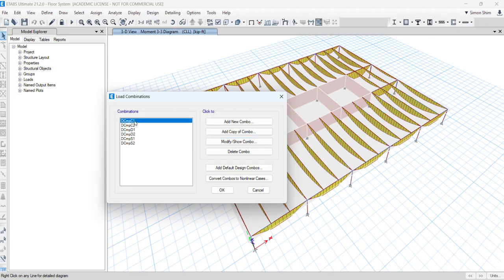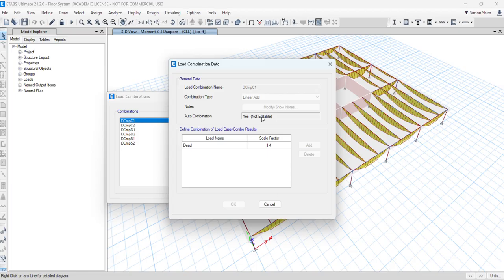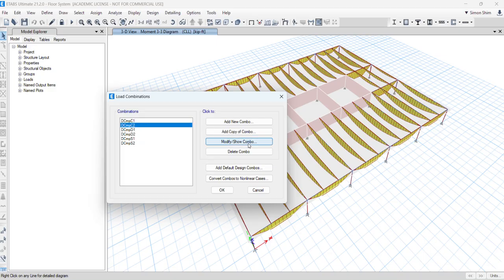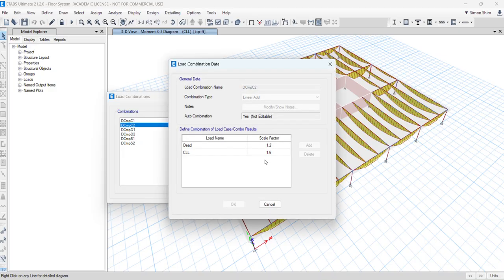But it also checks the phase one, which I'm going to explain in the composite floor framing design, because of the construction sequence. We need to check the beam size and its behavior under temporary loading during the construction phase. So C1 and C2 are going to be used during construction, basically before the concrete gets cured.